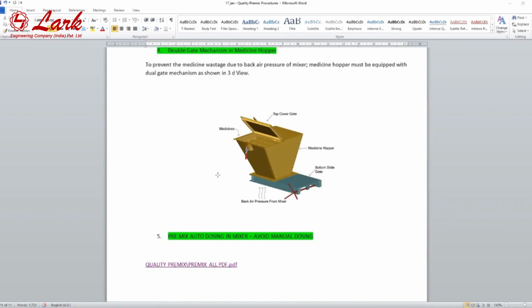We can charge this with different premix, complete premix, and as per the formulation and as per the recipe requirement, all these premix goes to this load cell based weigh hopper, and this weigh hopper, as per the command from the PLC, guides the premix directly to the mixer, automatically maintaining the dry and wet cycle, automatically maintaining 0.25% weighing tolerances, and totally this is an automatic PLC control system with the reporting system.